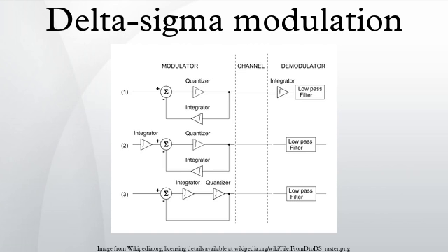The delta-sigma analog to digital conversion: the ADC converts the mean of an analog voltage into the mean of an analog pulse frequency and counts the pulses in a known interval so that the pulse count divided by the interval gives an accurate digital representation of the mean analog voltage during the interval. This interval can be chosen to give any desired resolution or accuracy. The method is cheaply produced by modern methods, and it is widely used.